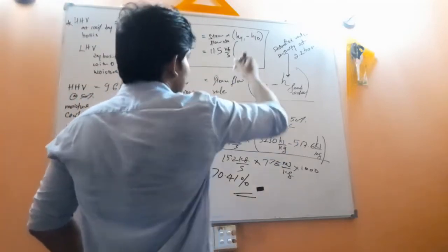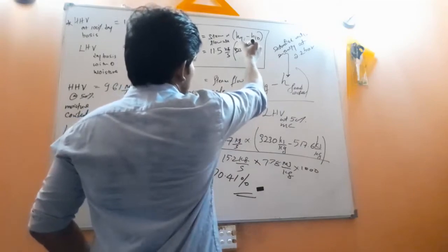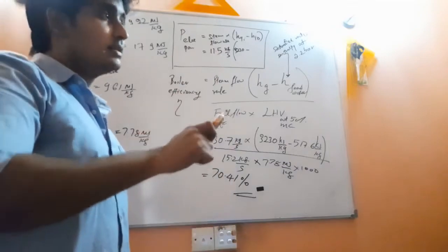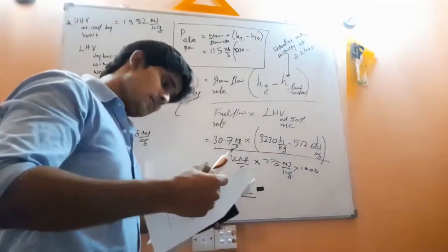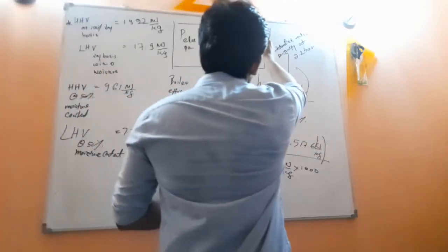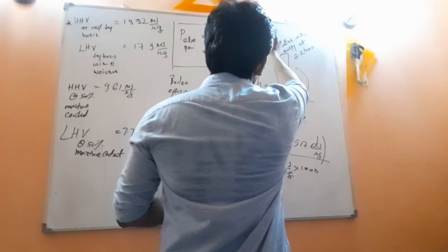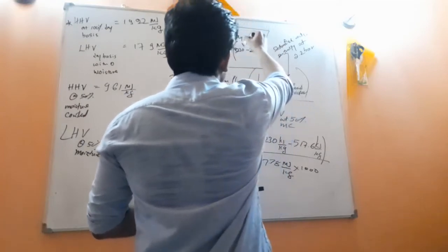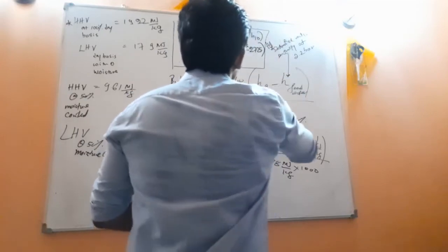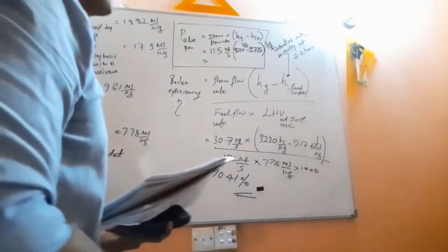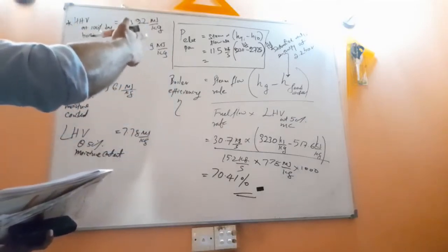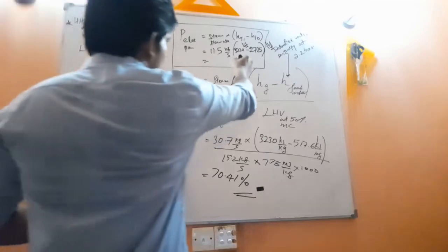The inlet enthalpy is 3230. The enthalpy at the end of the expansion is 2725. So units are kilojoules per kilogram here also kilojoules per kilogram. So kilograms per second times kilojoules per kilogram means kilojoules per second. Kilojoules per second means kilowatt.